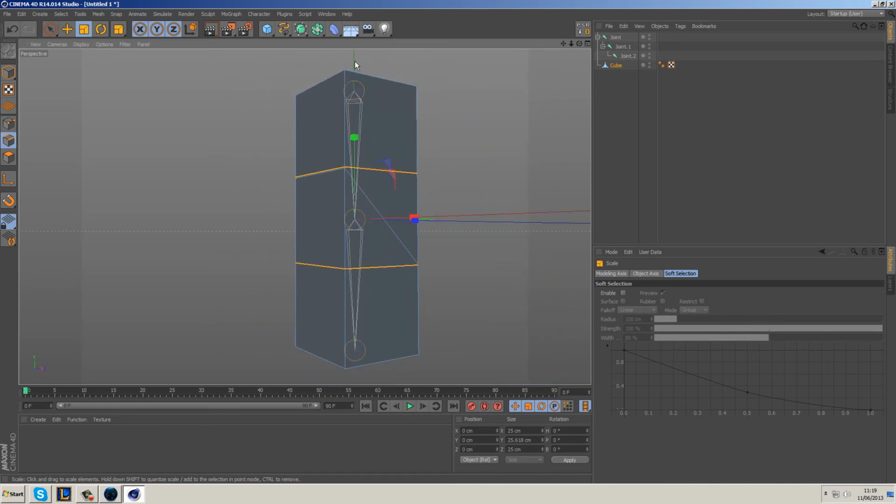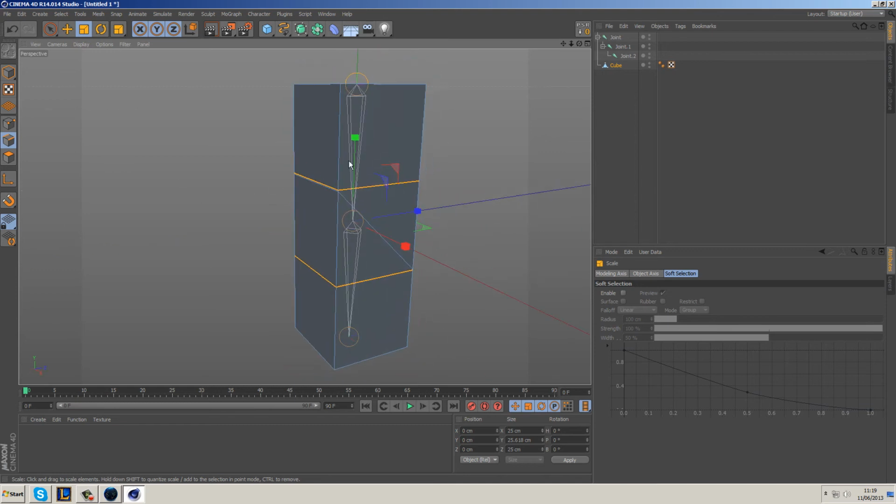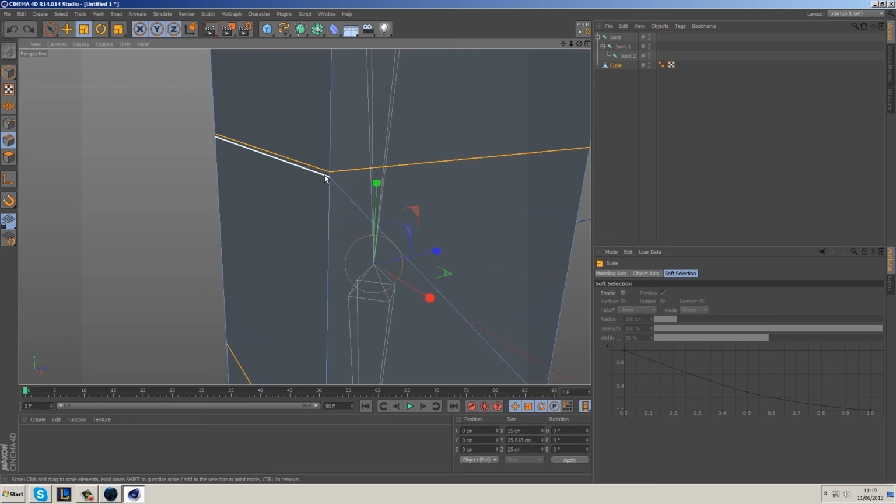The reason we want it as close as possible to this maximum length in which we manipulate these points is because if it's further up like this, it will stretch down at some point, and that's where you're going to get the texture stretching. So if it's as close as possible to the edge here without overlapping, we're not going to get as much texture stretching.